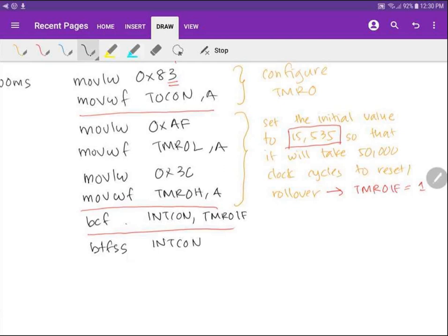That is because when you press the switch it becomes clear, and then we want it to skip. Of course here you can do that as well. So we are checking the timer 0 flag bit. If it's not 1, what should you do? You wait.